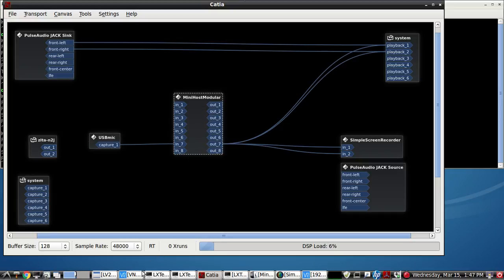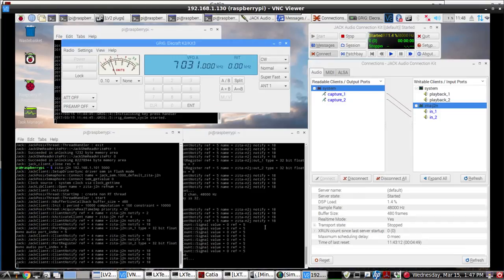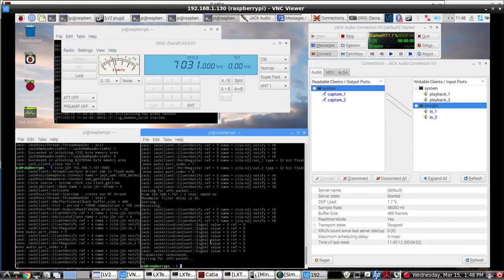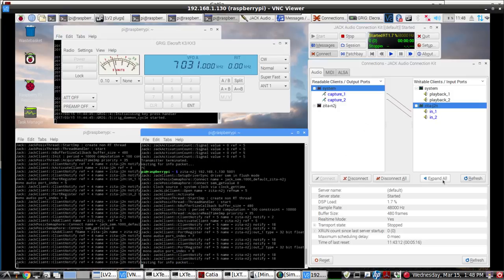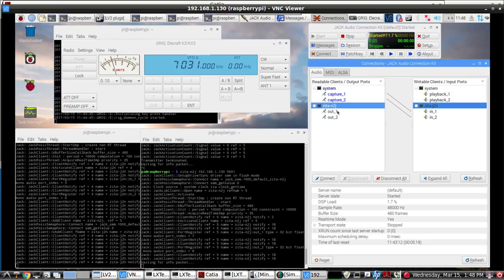So let's go back to the Pi and get this second one set up here. Again, we want to receive audio, so it's from the net to jack. So it's Zita-N2J. This would be the IP address of the receiving part and a different port number. So we have the 130 is the Pi, and let's go ahead and register that, and there it is, showing up in the connection bay. So we want this audio to go to the Pi's own sound card, and then go out that audio cable to the audio-derived key switch. We'll hit connect.